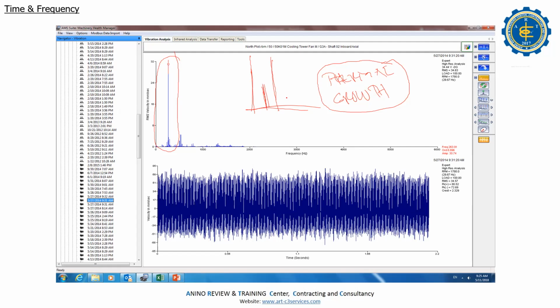Sir, in your vibration testing, do you check radial also? Radial and axial? We don't have triaxial before, so we have X, Y, and Z. We have 3 readings: inboard 3 readings, outboard 3 readings.